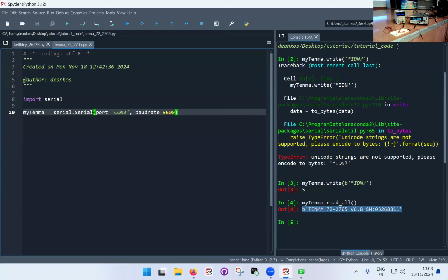First of all, it makes it a little bit more intuitive when you're using it, because in 2 months' time, I'm not going to remember how I implemented all the basic functions of the Keithley, right? But I will remember that I can go for Keithley dot set output. It's a way of detaching yourself from the low-level code that you send to the instruments. It's a way to make things modular.